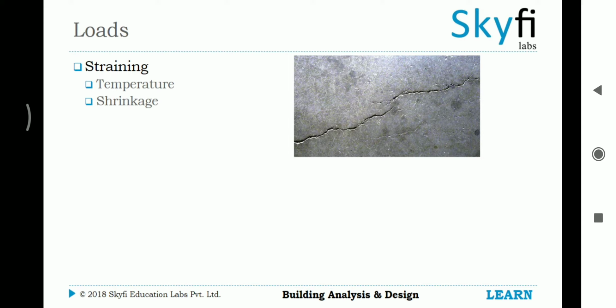Shrinkage, an effect in concrete structures, is the contracting of a hardened concrete mixture due to the loss of capillary water. This shrinkage causes an increase in tensile stress, which may lead to cracking, internal warping, and external deflection.